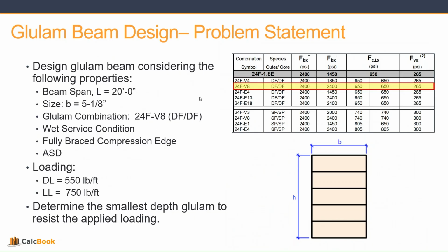We are in a wet service condition. Our compression edge, the top edge in this case, is fully braced for compression, so we'll be able to ignore the C_L factor, the stability factor. We're going to be using ASD loading.